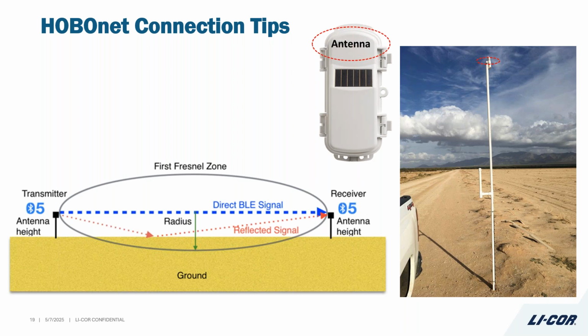And we highly recommend, and we will help walk you through this, getting all of these loggers set up at your home base or in your office. Turn on your base station, hook them up, connect all of these radio motes to each other before you go out in the field and deploy these. Once you go out and you do deploy these, deploy them high enough, deploy them so that you would be proud of it. Wires are covered. It looks good out in the field, right?